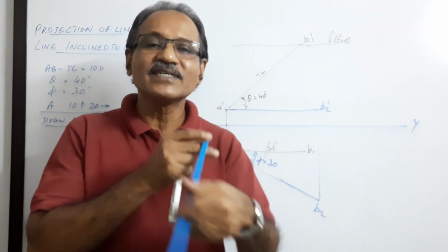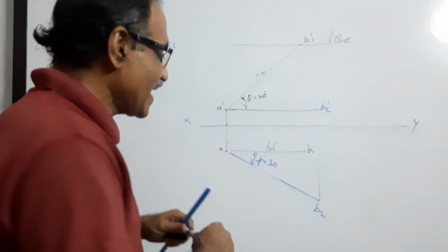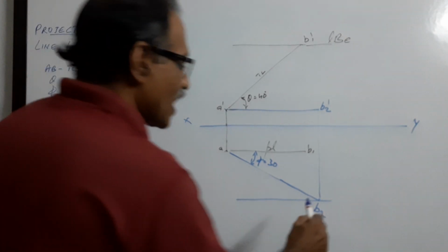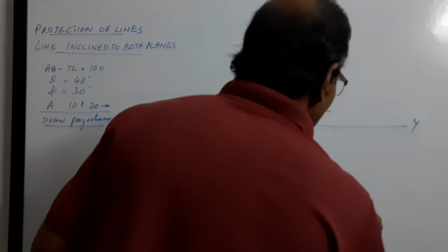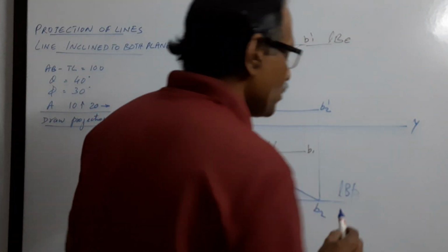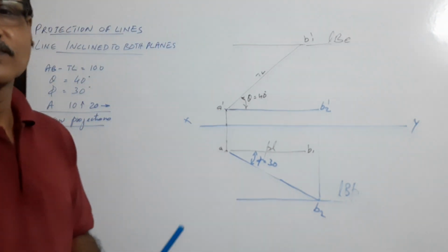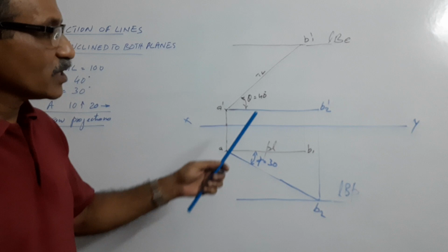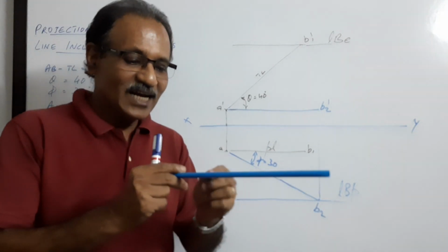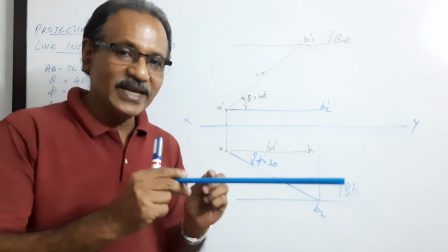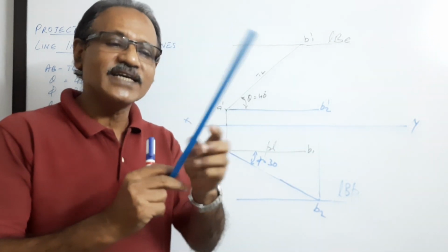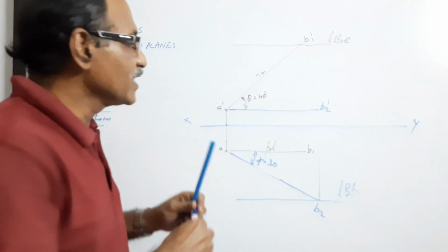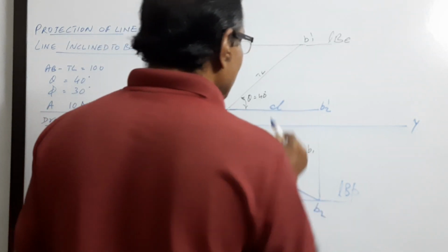What's the plan of this circle? Plan of this circle is a line which passes through B2, and I call this locus of B in plan, LBP. Locus of B in plan, LBP. As long as phi does not vary, the elevation length cannot change even if it is moved. Phi same, so the elevation length is L cos phi. So I call this elevation length, EL.